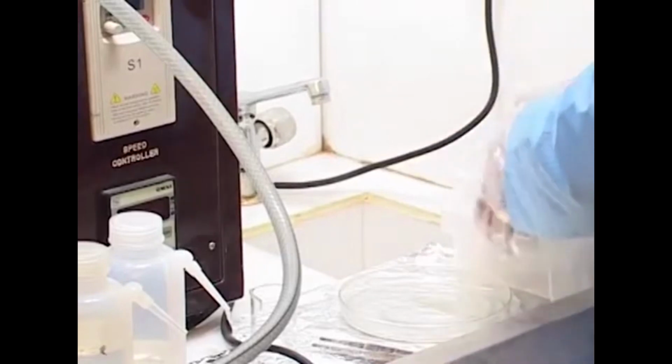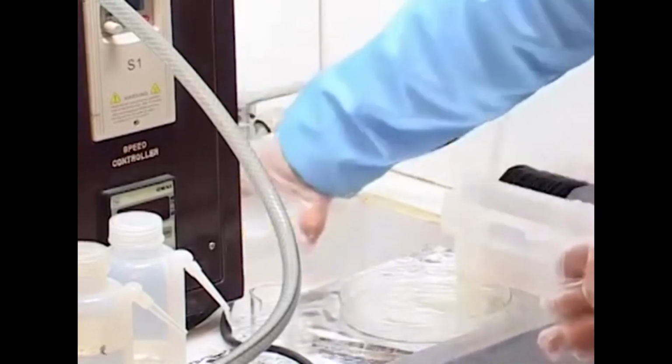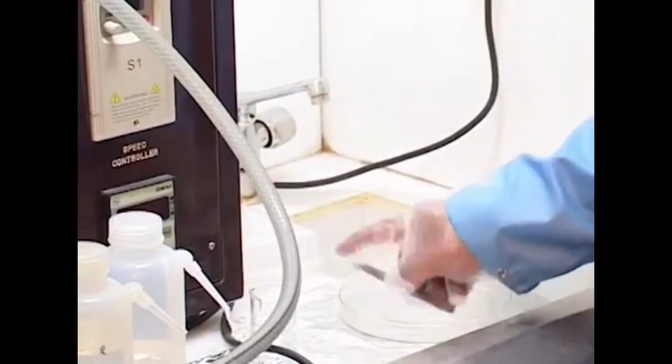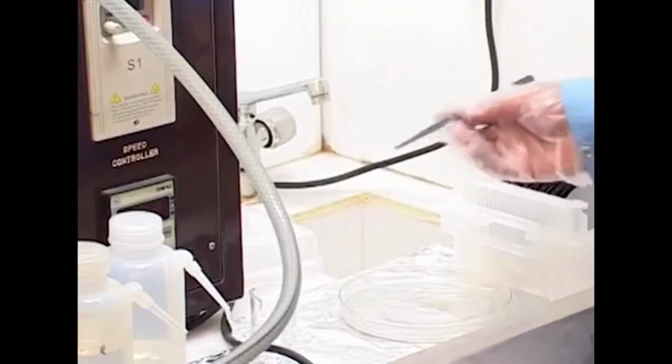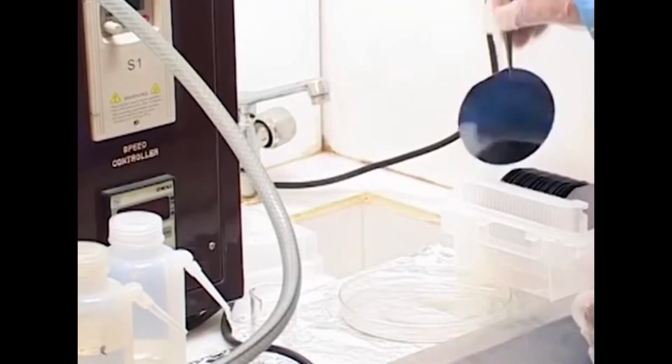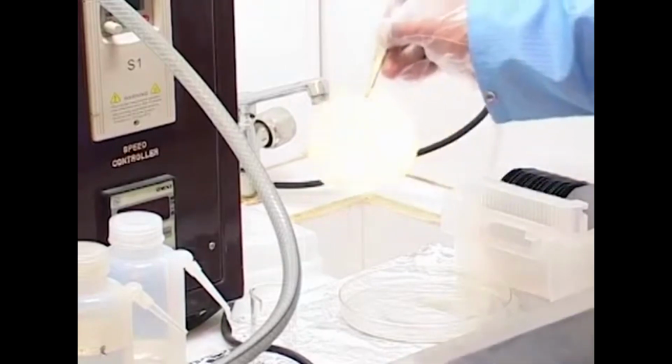As you're seeing, this is the wafer box. This process only has to be done within a fume hood, because this prevents the chances of the wafer getting contaminated by the dust particles of the air. So we take a wafer out using a tweezer, as you can see here.